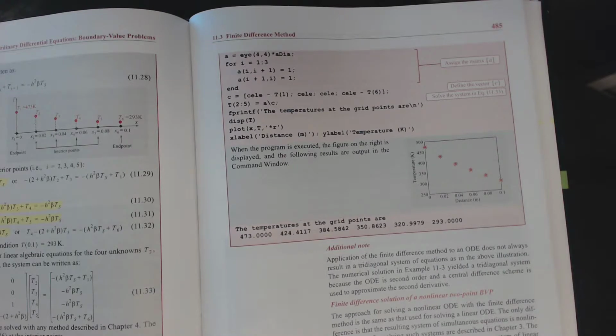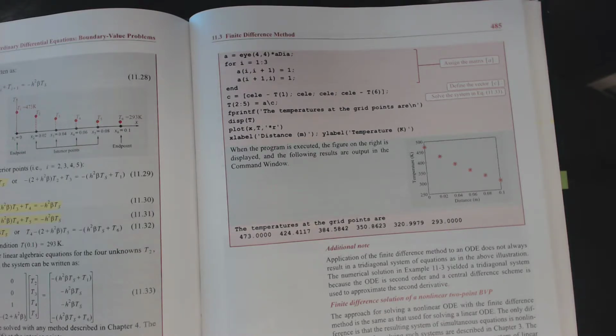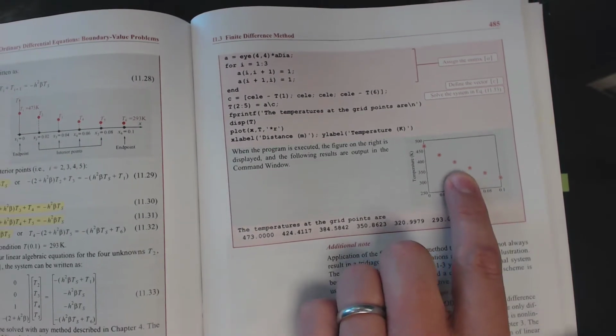Everything comes out in balance, and if you've done all the things right and not messed up a negative sign somewhere, then they come out in kind and nice alignment in an arrangement that satisfies the discrete needs of the differential equation. Boundary conditions are easy to satisfy because they don't move. The boundary condition is what it is. The temperature there is going to be exactly what the book says. The important part is that the derivatives and the relationships between the different orders of derivatives making up the differential equation in between are correct. So this curvature satisfies all the heat transfer equations, satisfies convection equations of heat leaving, and you're set to go.